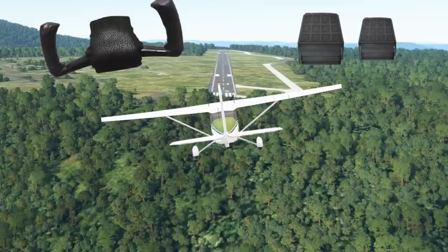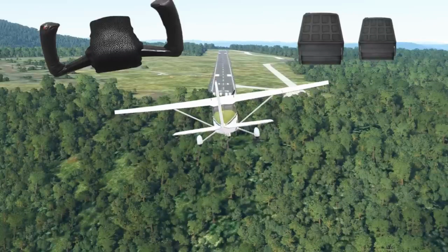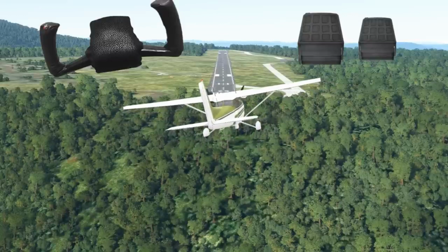While the airplane is decelerating during the after-landing roll, more and more aileron is applied to keep the upwind wing from rising. Since the airplane is slowing down, there is less airflow around the ailerons and they become less effective. At the same time, the relative wind becomes more of a crosswind and exerts a greater lifting force on the upwind wing. When the airplane is coming to a stop, the aileron control should be held fully toward the wind.